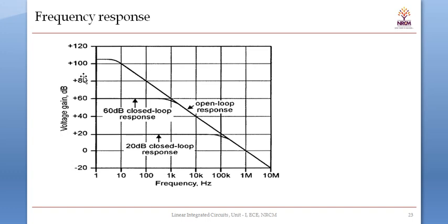So here generally for the amplifier, as the operating frequency is going to increase, the two effects are more evident. The first is the gain of amplifier decreases. So as the frequency is going to increase, the gain decreases and the phase shift between output and input signal increases. So as frequency is going to increase, the phase shift between output and input is going to increase and gain is going to decrease.